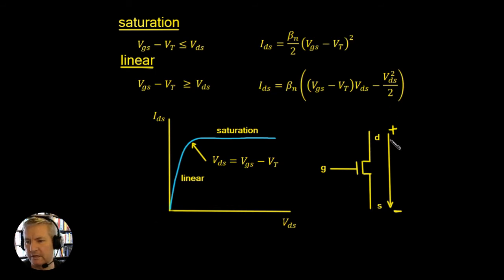So we know that this here is the conventional current flow. So we've got the conventional current flow of this device in the y-axis here, if you like. So that's the current from the drain to the source through the device, which is in this direction. But of course, we know from what we've done previously, this is the NMOS device. The actual current is carried by electrons which travel in this direction. So the actual electron flow is in this direction here.